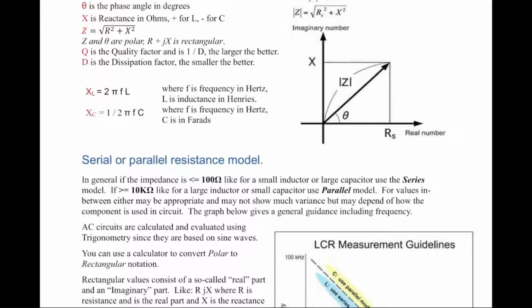because, as I showed earlier, the reactance doesn't change, but the inductance seems to change between serial and parallel, which tells you that it is actually a calculated value. When it does the parallel mode model versus the serial model, it uses a different calculation, and that calculation can come back with a different value. So that is what you learn from that, that is how it works.